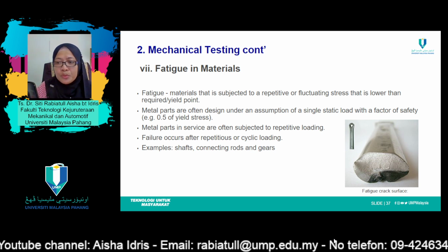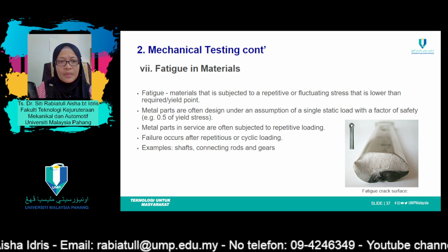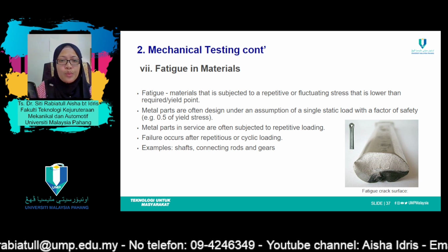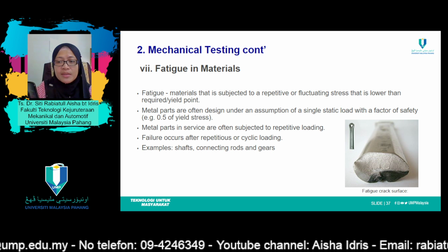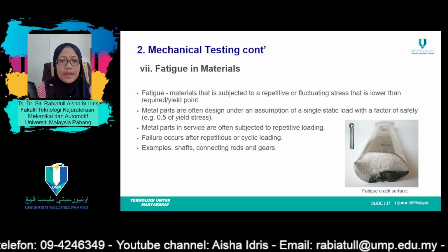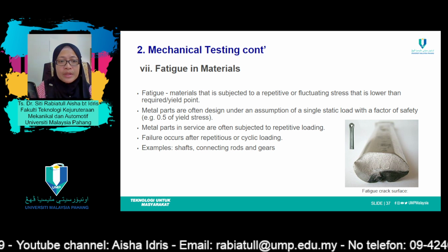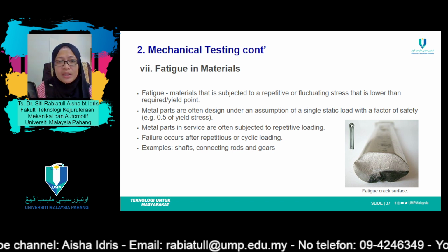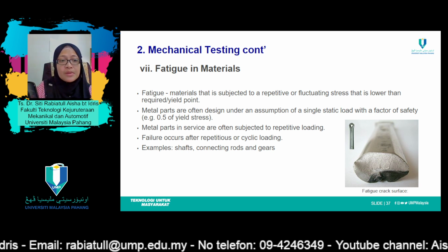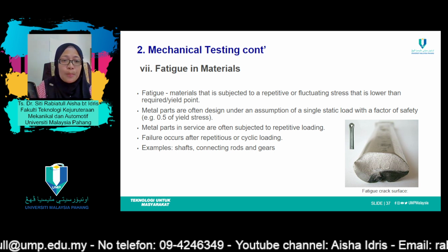Okay, so move on to the next type of testing, which is the fatigue test. Fatigue test helps in determining a material's ability to withstand cyclic fatigue loading conditions. By design, a material is selected to meet or exceed service loads that are anticipated in fatigue testing applications. Cyclic fatigue tests produce repeated loading and unloading in tension, compression, bending, torsion, or a combination of these stresses. Fatigue tests are commonly loaded in tension to tension, compression to compression, and tension into compression and reverse.